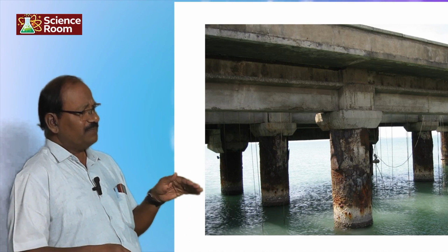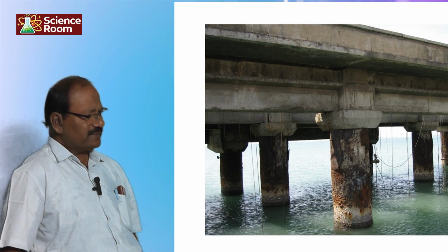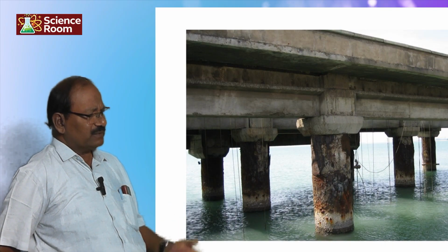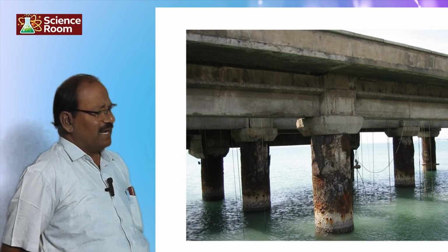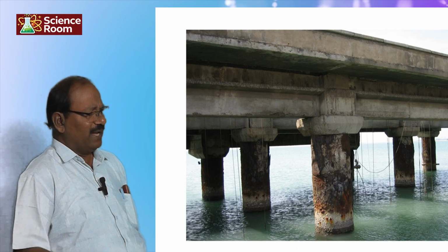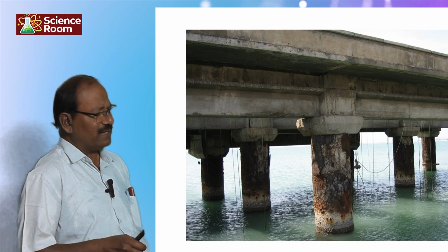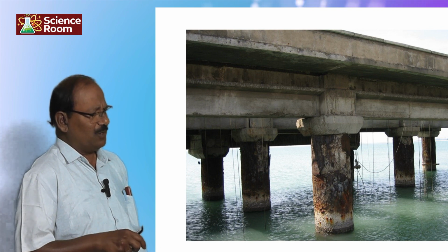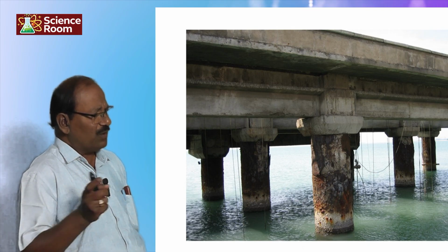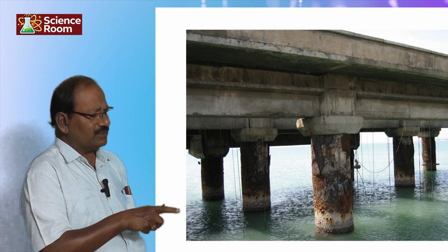You can see the high tide and low tide here. In that you can see small attachments. These are nothing but bacteria that go and get attached to the steel plates, and then consume the organic matter in the seawater, and excrete. The excreta of these bacteria is highly acidic, with low pH, and it affects the steel, which also gets deteriorated. One is the chloride attack. The second one is the bacterial microbial activity that also spoils the steel.